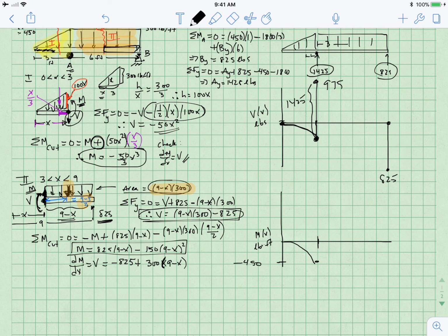It's a linear equation, if you take a look at it. So what's happening with shear is it's just doing something like that. So across the beam, we start at 0, drops, the shear value rises suddenly, linearly drops, and then at the very, very end of the beam, there's no shear because it's being supported there.